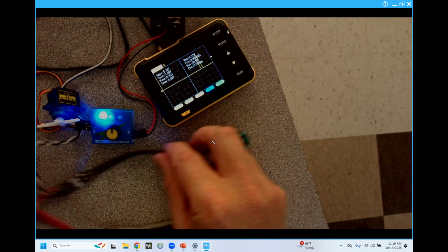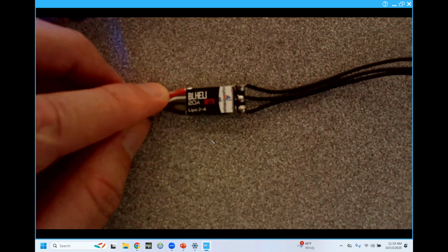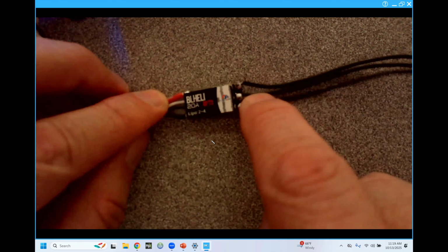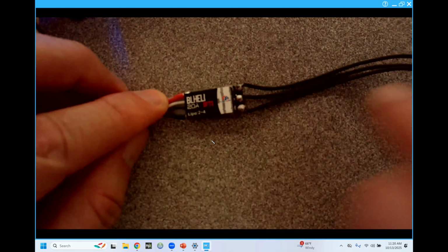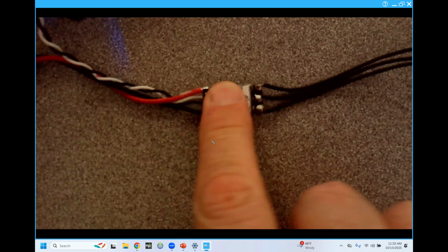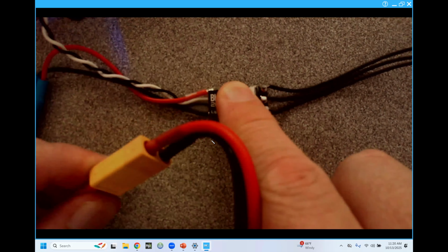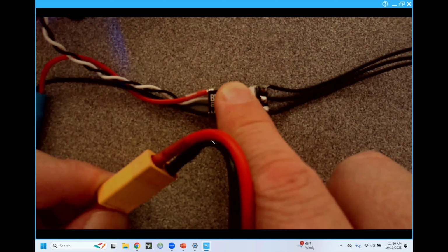Your job will be to solder the speed controller, which is actually pretty simple, because you have 3 wires to solder. And there's actually a hole that it goes through, so it's going to be very, very easy to solder. The other end, well, you do have another job for the other end, which is you have to get the power leads to the output of your flight controller.